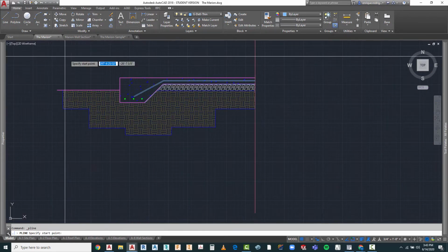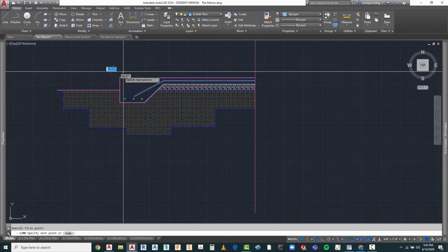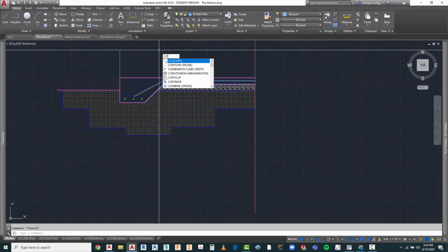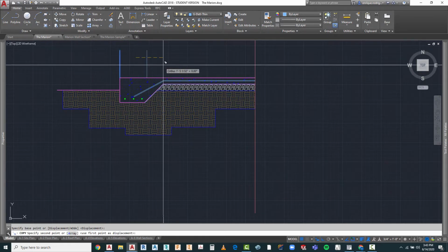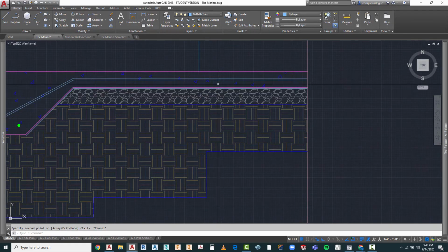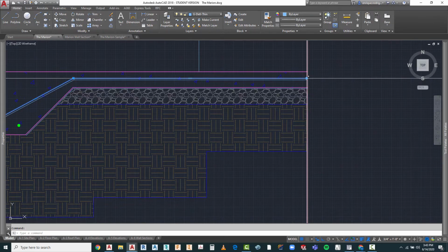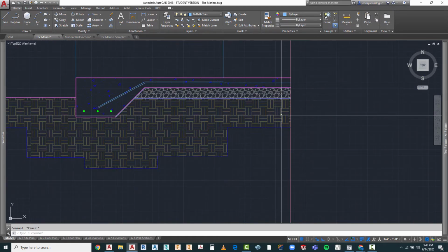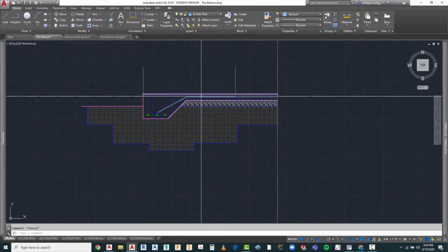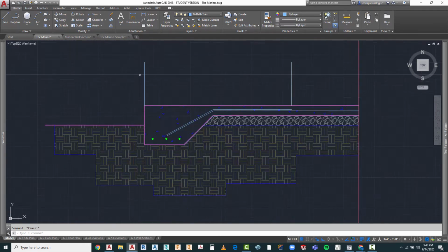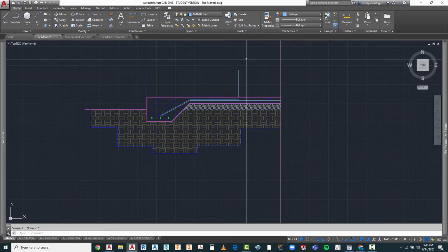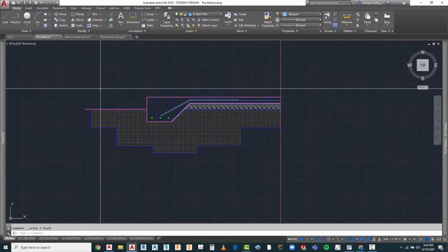And I'm going to draw a line in here to see where my 60 inches is. Now, each architect and engineer may want this doubling up a little bit different, but I'm going to go ahead and move that 60 onto there. And what I can go ahead and do now is bring that to line up at that point. So there's my double reinforcing around the perimeter wherever our walls are going to be located. I can now delete this. Let's go ahead and delete that.